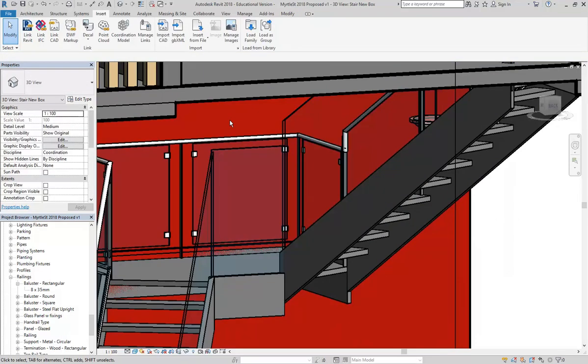Yeah. If you have a look at the stairs here, where you would never have noticed it before, but now you'll see that where the two stairs join from each flight, they've extended the handrail a little bit. That's one way. Another way is to slope the handrail on the flat landing, which you'll see all the time as well. You won't notice it until you've done some stair design, and then you'll notice it every time you walk up a stair that's got two flights.